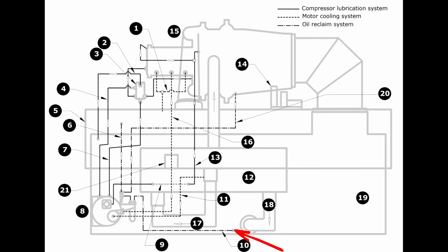A lot of factors dictate how much flow goes through here. The level of the machine has a huge impact, and even slight elevation differences from one end of the chiller to the other, if it's not perfectly level, have a big impact on where that refrigerant distributes and how it's going to interact with our eductor system. So there are many factors at play that affect where that valve needs to be for proper flow on the eductor.